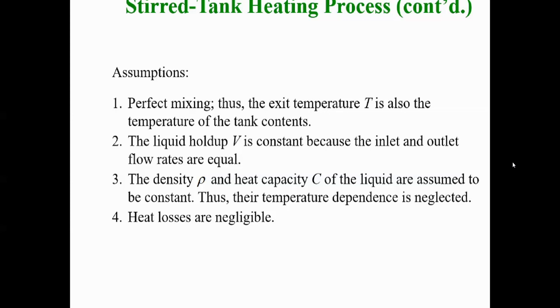And the liquid holdup V is constant because the inlet and outlet flow rates are equal, so we do not consider evaporation in this case. Number three, the density rho and heat capacity C of the liquid are assumed to be constant, thus temperature dependence is neglected. And number four, heat losses are considered to be negligible.